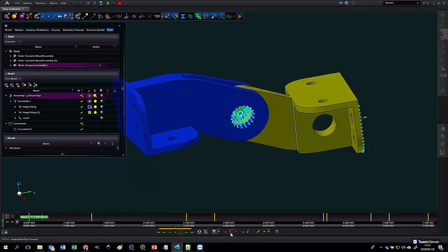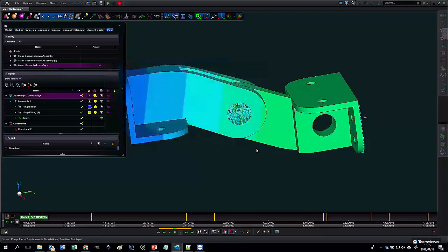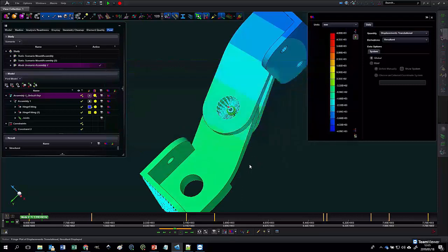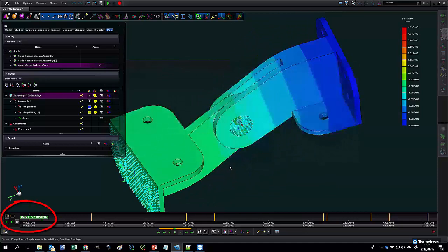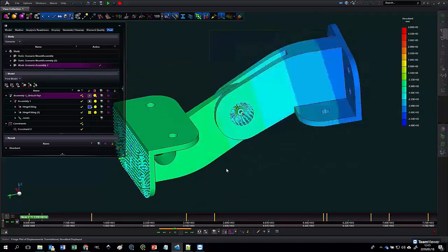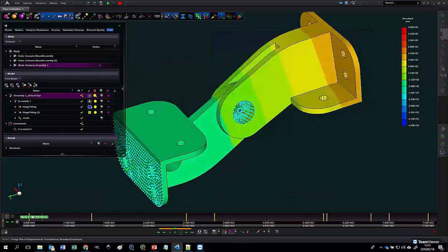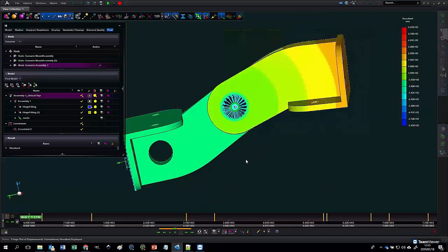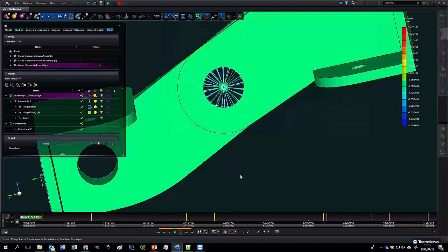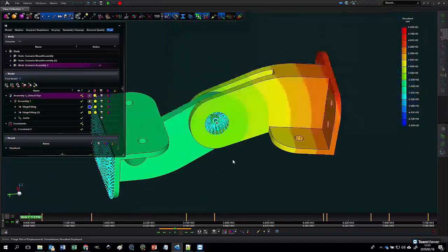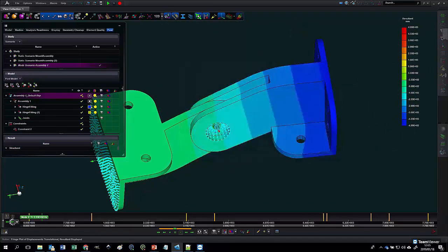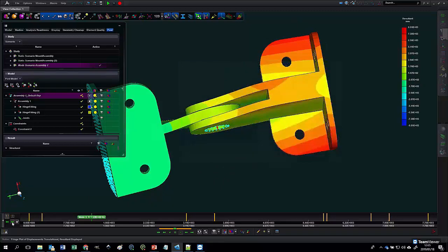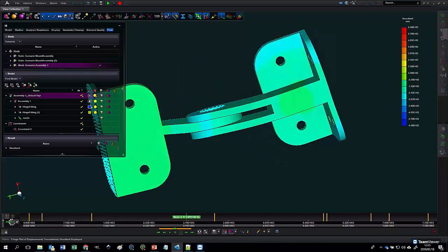So firstly, what you should note, Apex in the post-processor jumps to the first non-rigid body mode. So it starts with the lowest mode that isn't the rigid body mode, and that's why it displays mode 2 by default, whereas mode 1 is the free body mode. And here we can now see that our body rotation is indeed the way it should be in the first place.